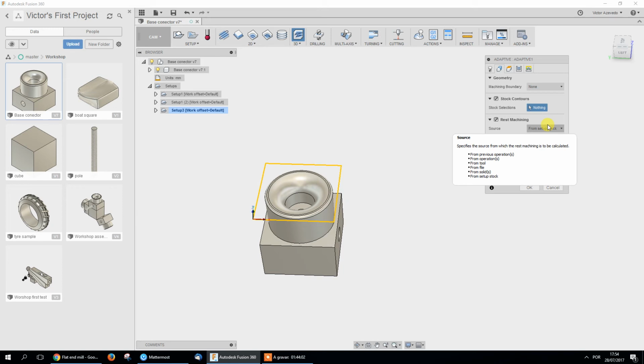Instead of starting with a small drill or small end mill and removing just a little bit of material, I can get a big one like the 12mm and remove a lot of this. Then you'll leave some stock with the leave option.